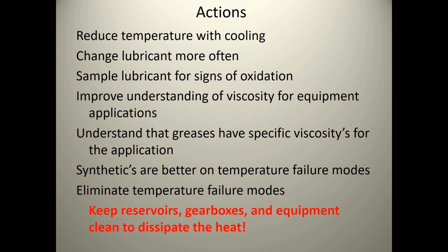This is one of the things I sometimes argue with corporate procurement departments about. They don't want to spend the 2 or 3 times more for the synthetic, but they don't understand that the lubricant's going to last so much longer, and you're going to have more equipment life. But again, sometimes we have to eliminate these temperature failure modes. Keep your reservoirs, gearbox, and equipment clean to dissipate the heat. But look, where's the heat coming from, and how can I reduce that heat?